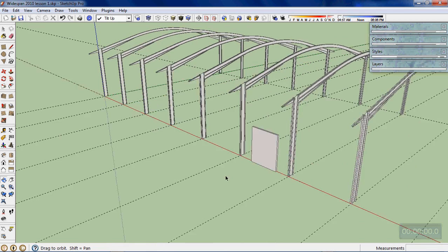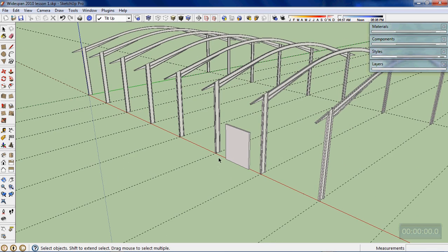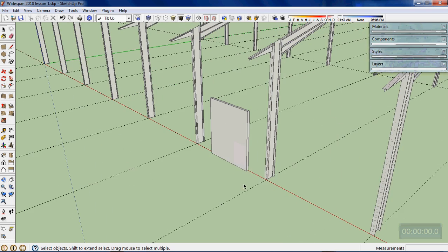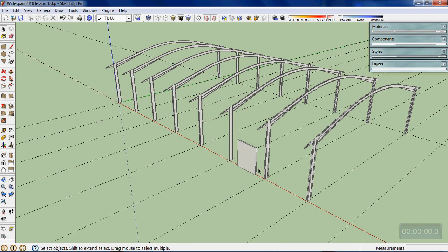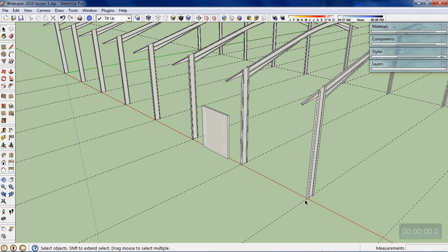Now with that, what I'll do next is I'll do a sail past detail on these concrete tilt-up columns. I'll actually sail the concrete wall about 200 millimeters past the center line of the column. So once again, I'm grabbing my tape measure. I'll do a set out line in the red axis direction this time of 200 from that place, and I'll do one 200 back here.